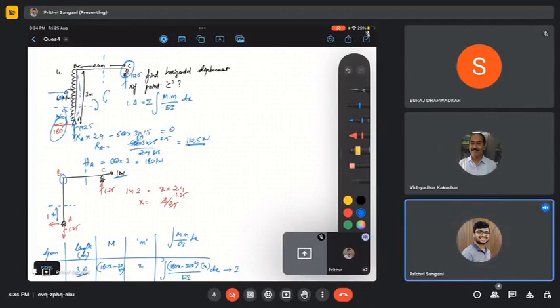But in the initial days, for second years and third years, getting that in mind is kind of difficult, so that's why we usually call it sagging and hogging. Otherwise, it is always taken as tension: the portion where we have tension, we take it upwards, and downwards as compression. That's what the thing usually is.